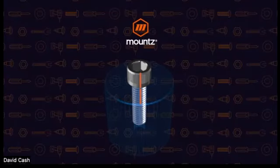So there would need to be some testing done during the assembly process to capture what the actual torque was when the fastener was applied, and then develop an uncertainty value or a correlation between that value and the value at the auditing process, based off of whatever test you might consider. Which test is going to be best depends on which test you think is going to provide you the best results. In all of these cases, there's going to be some type of change that may occur because the friction values are going to be different. The material may do some different things than it would have done during the assembly process.